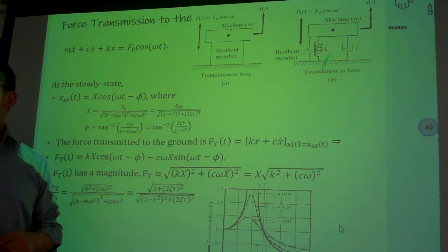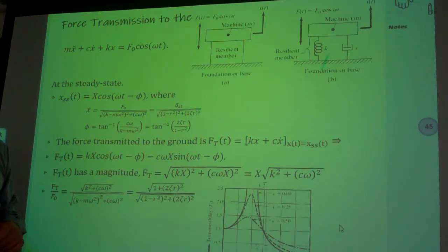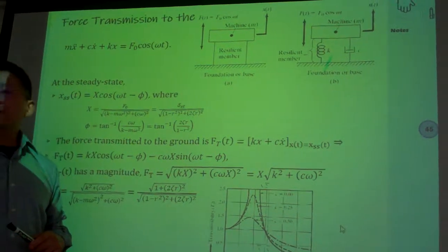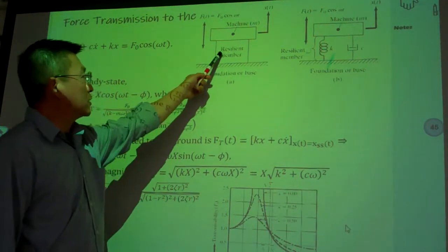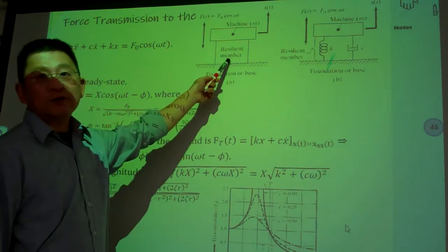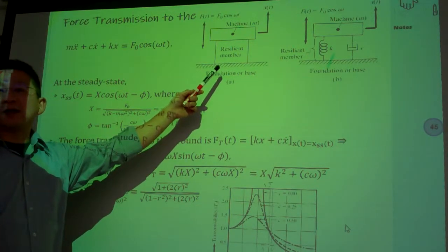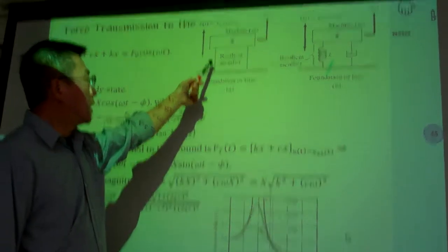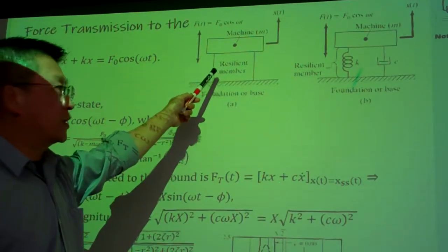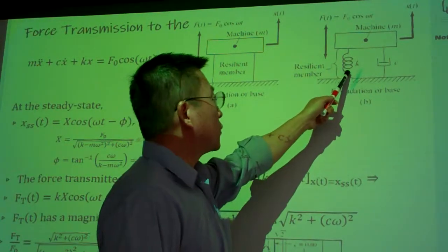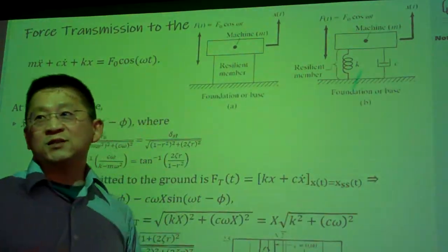In particular, I believe they not only set up the facilities like the electricity to get that working, but also the mounting installations. One of the installations includes what is called the resilient members. That is a term from our textbook. Basically, this is the isolation design. In principle, this elastic and damping material can be simulated by a single spring plus a single damper, okay, the simplest way.